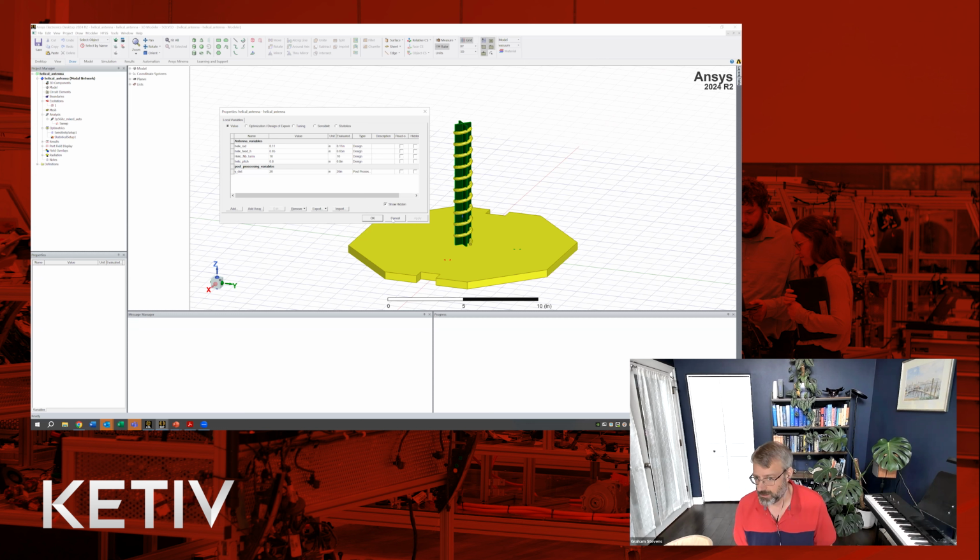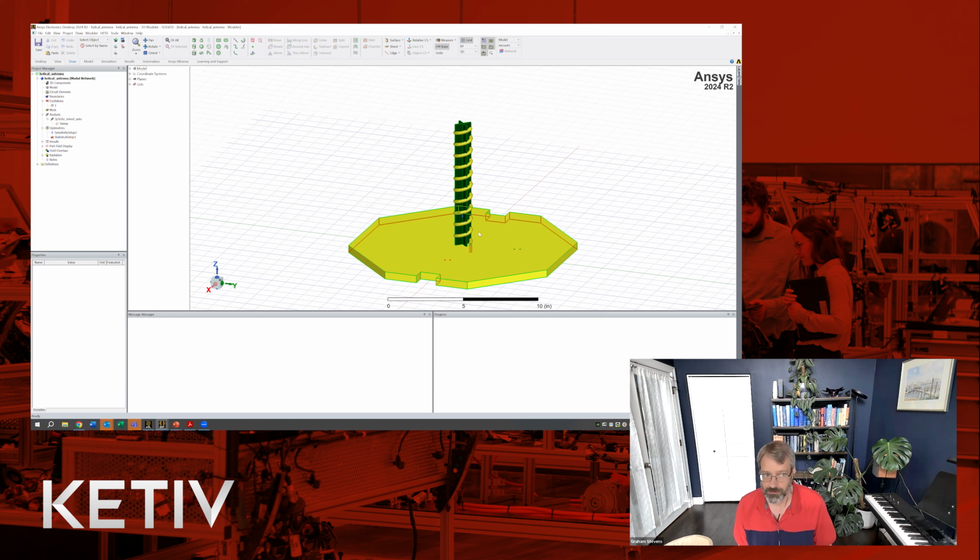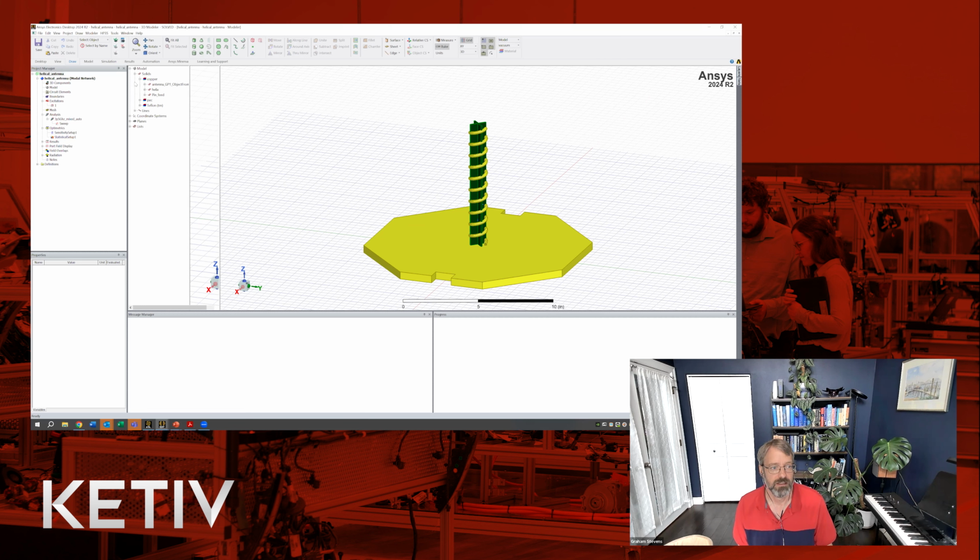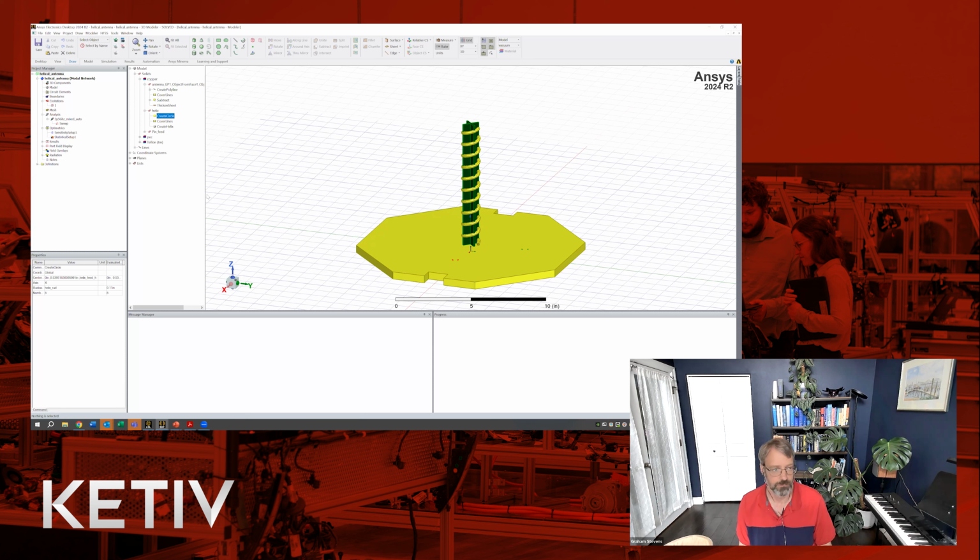And so the first step is to have your model laid out in such a way that you have the underlying geometry, whether it's the helix here, where we do create circle, and we have the helix feed here, call that as variables, where you have geometry that's modifiable and parameterized, and most HFSS users are familiar with this sort of model start.